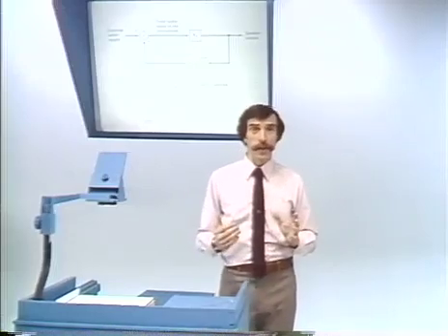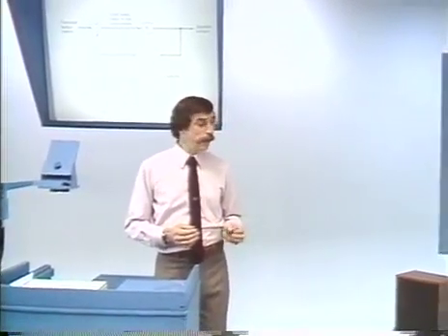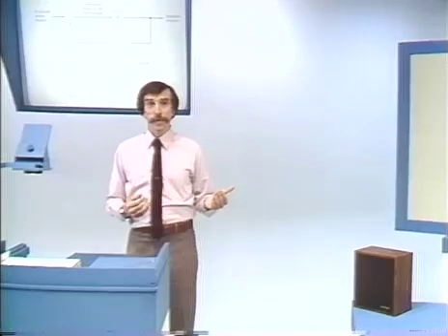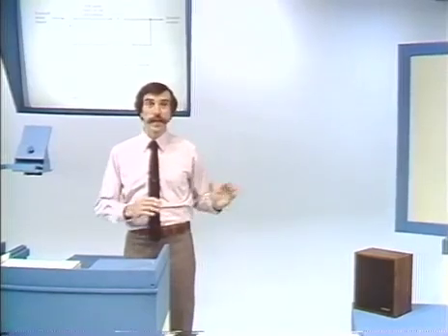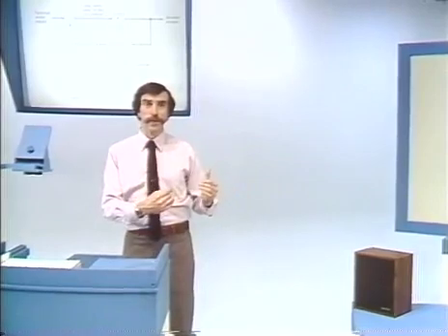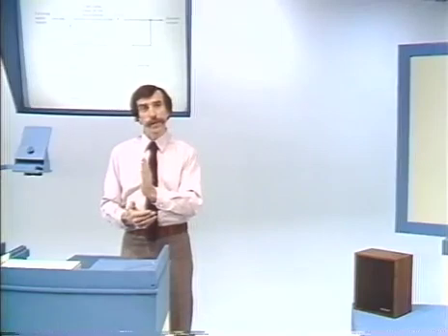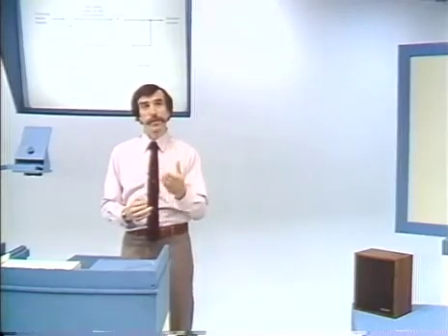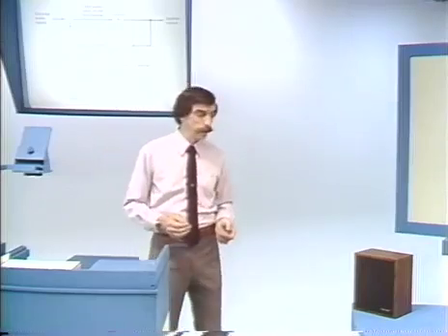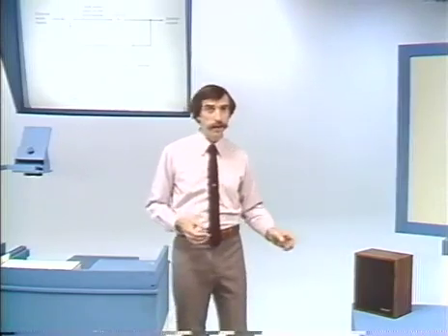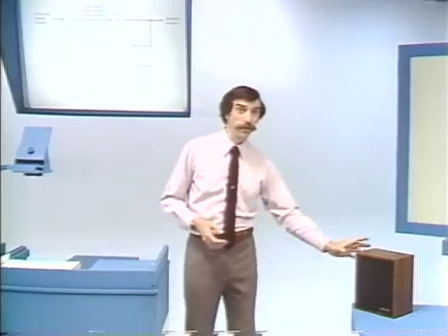Just to illustrate that, let's turn the speaker on, and we'll demonstrate feedback. Right now, the system is stable, and I'm being careful to keep my distance from the speaker. As I get closer, K2 will increase, and as K2 increases, eventually the poles will move into the right half of the s-plane, or they'll try to. What will happen is that the system will start to oscillate and go into nonlinear distortion. As I get closer, you can hear that we get feedback, we get oscillation. I guess neither you nor I can take too much of that.